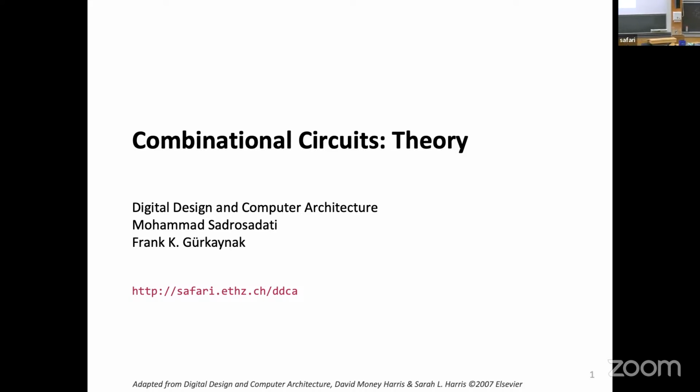What we should take home was that these transistors can work as switches. We can manufacture them very efficiently. They fall into two categories. There was the PMOS transistors, whose job was to work when the output of our digital circuit switches from 0 to 1. It's this guy doing the work. And when you had an NMOS transistor, his job was to pull things down to a lower level. We worked with these two levels: a level 0 and a level high, level 1. And we said, if we have only these two things, we can do wondrous things.